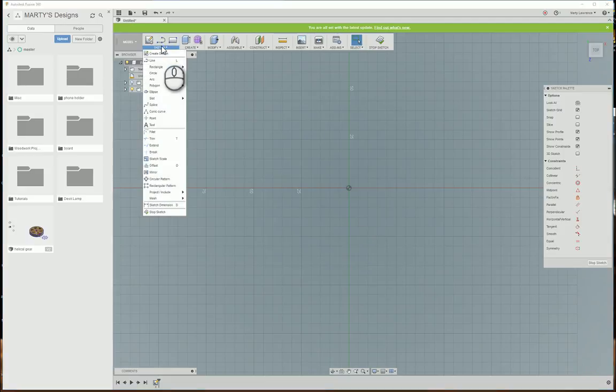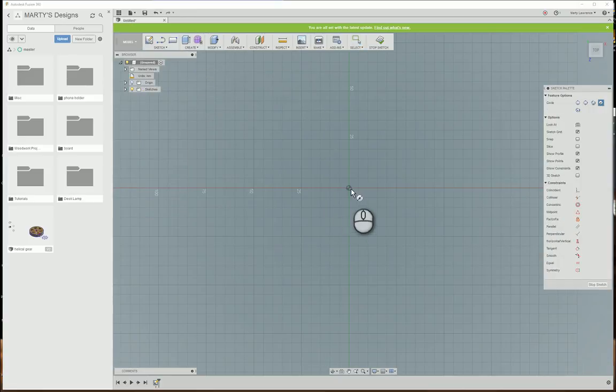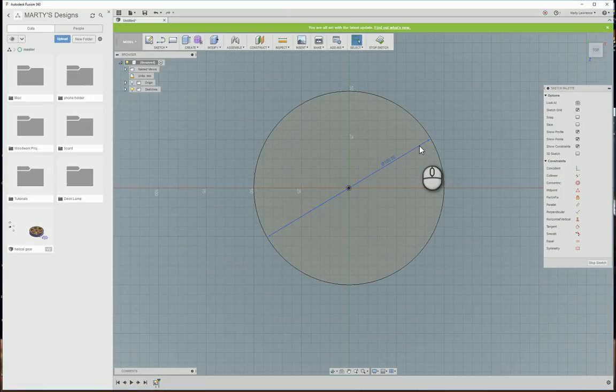Now the tool we're going to select in this sketch is obviously a circle tool, center diameter circle, and we can click once to start the circle, then we can drag it out to our size, which is going to be pretty hard to get 100 by dragging. So what we can simply do is type 100, and if I press enter it'll lock that size. Enter again, that actually finishes drawing that shape, and it should be highlighted.